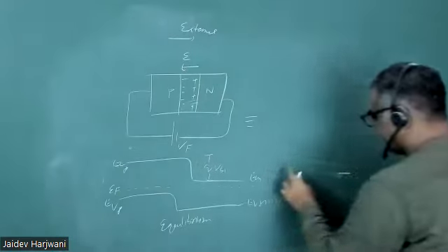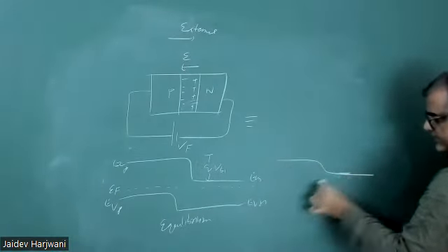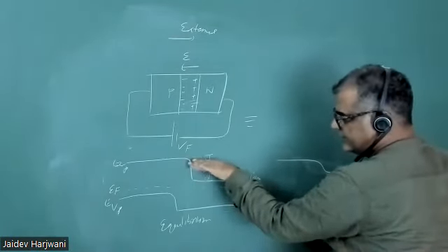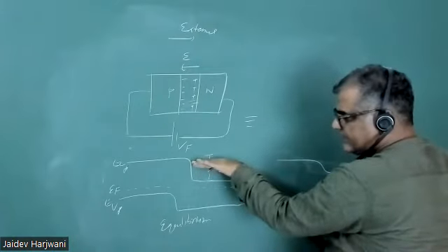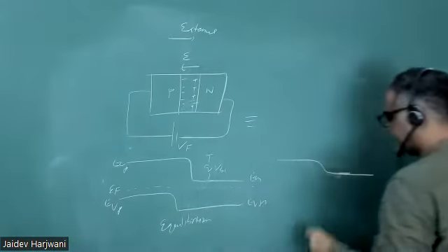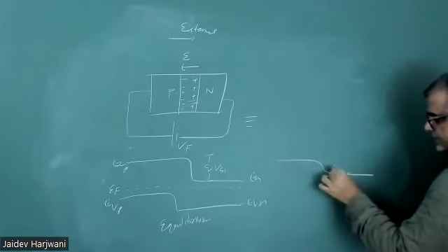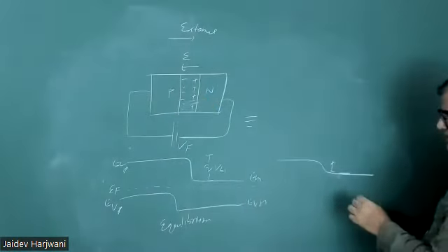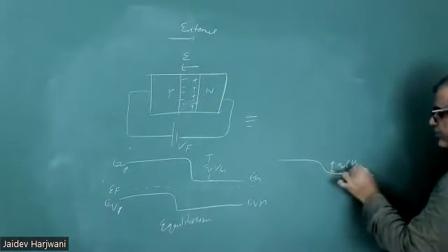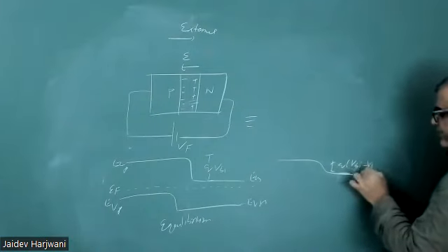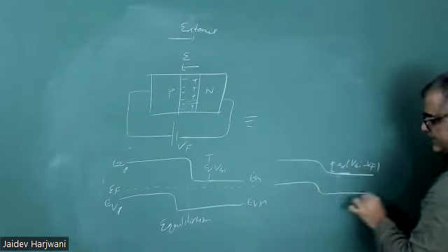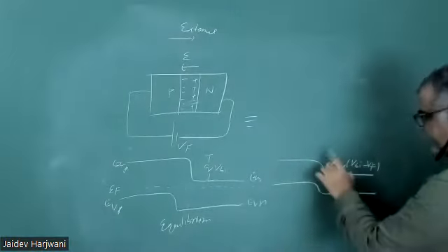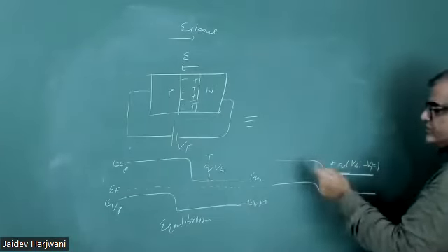अभी voltage इतना है, okay, built-in potential, और बाद में क्या हो जाएगा, अगर आप VBI के बराबर पोटेंशियल लगा दोगे, ओके, तो ये गैप कम हो जाएगा, and they will come to the same level and the current can flow, okay. So now if I apply voltage, this voltage is opposite to this built-in potential, so you will have, instead of Q VBI, Q(VBI minus VF), okay. Similarly, this barrier height will decrease, okay,